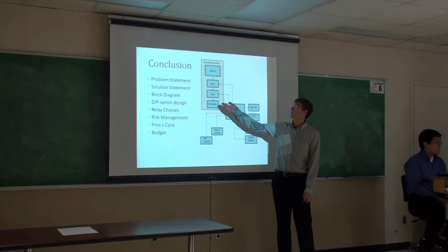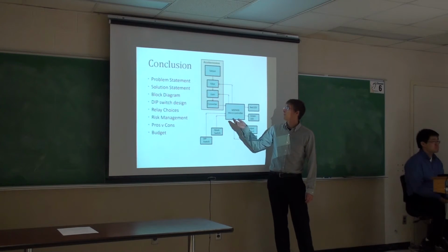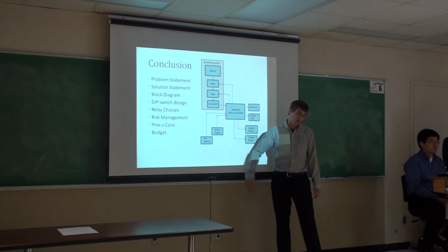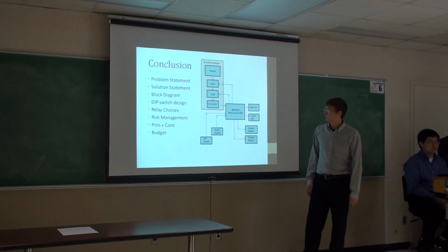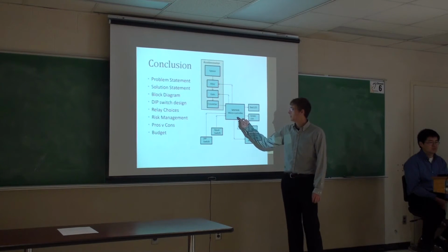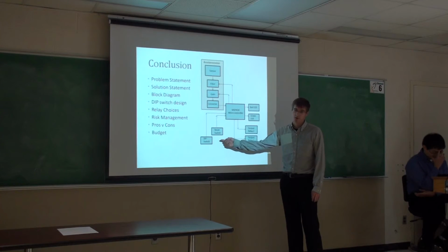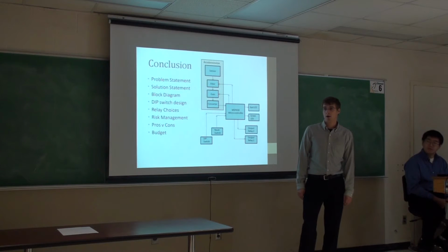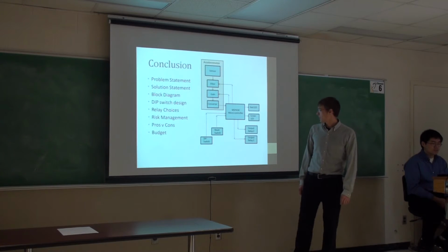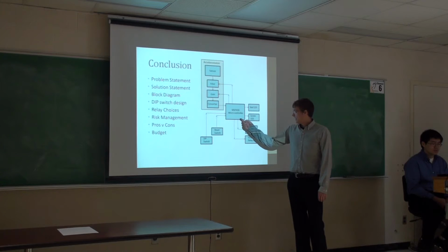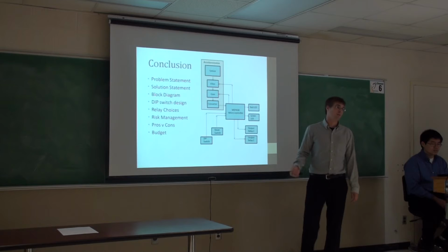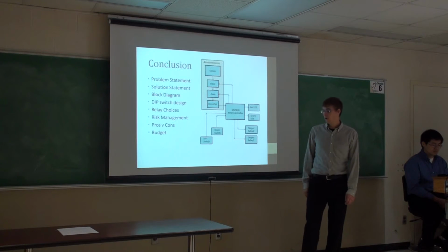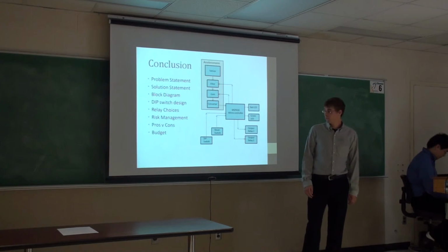And it is driven by a microcontroller. The accelerometer measures the G-forces, which sends digital output to the microcontroller and compares it to the dip switch. And the dip switch has 8 peak values and 8 RMS values that the user can set. And that information is compared and sent to 2 relays, which are 125 volt, 10 amp solid state relays that we're probably going to choose.